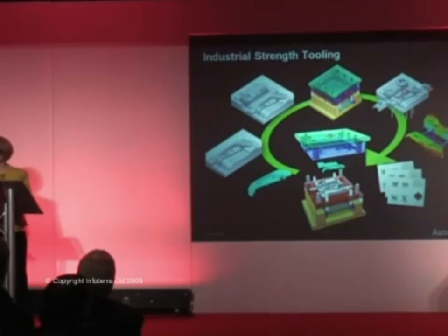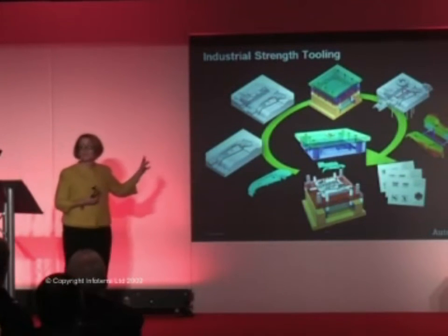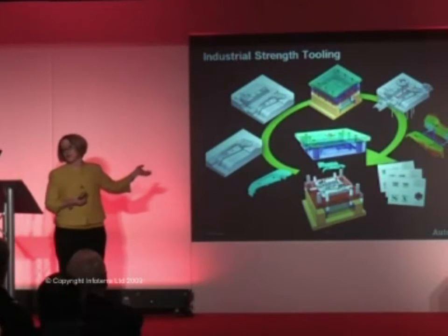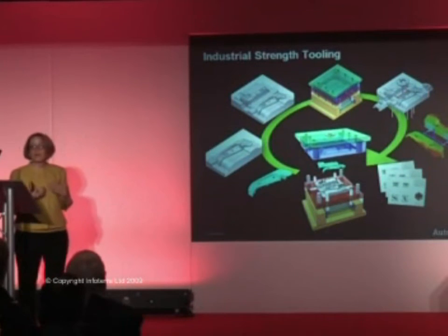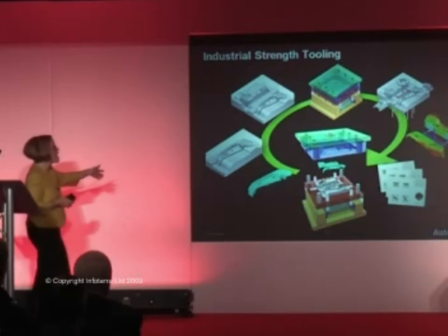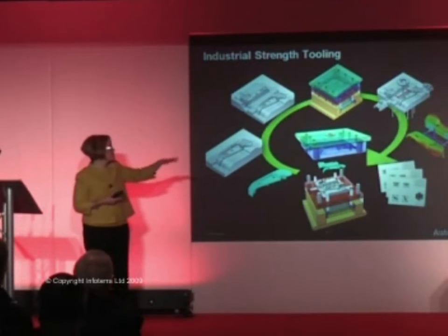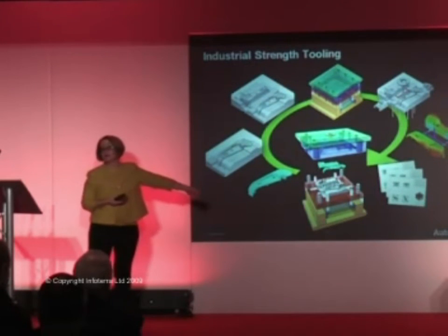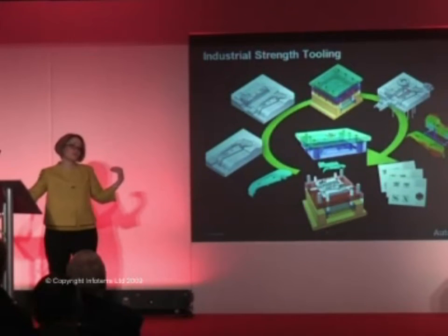We also just introduced in 2010 a tooling application. This will create molds for plastic parts, and it's built into Inventor Professional, and like many of our applications, it is very, very focused. It guides you through this whole process, creating the core and cavity, with a huge mold library, putting the gates and runners on, and even creating automatically, with really a button push, all of the different types of documentation that you need for the mold.